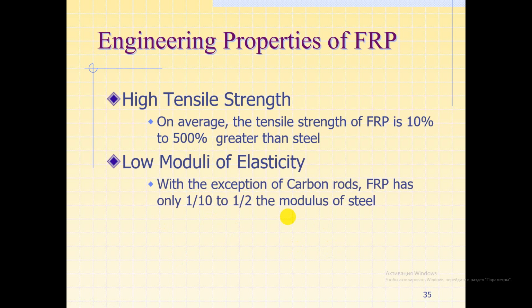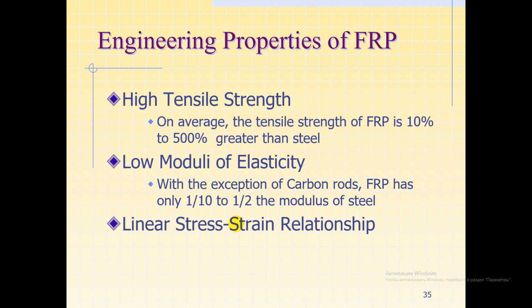With the exception of carbon rods, fiber-reinforced polymer has only 1/10 to 1/2 the modulus of steel. Linear stress-strain relationship. Very important characteristics.